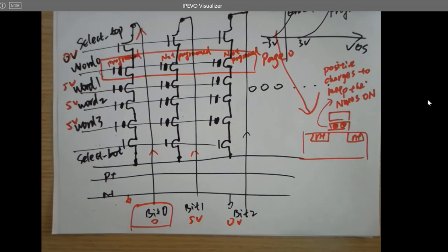However, in the schematic, when you're doing LVS, you probably have to think about how to do it. Just look at the library. There might be a device that has two gates, as a floating gate, so you can do LVS. There's no problem to draw it and fabricate it.